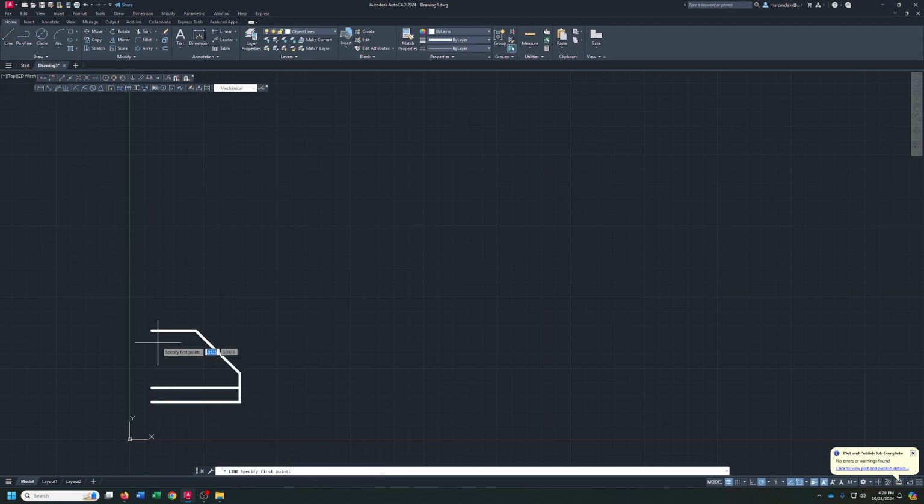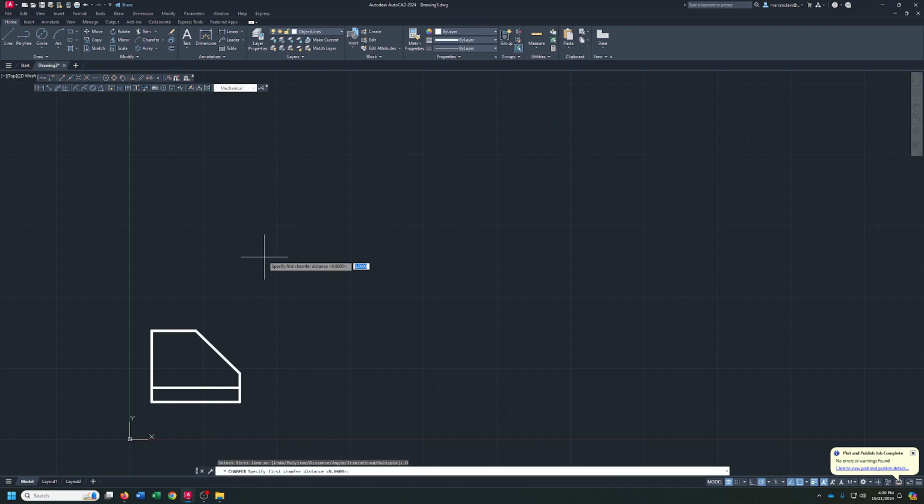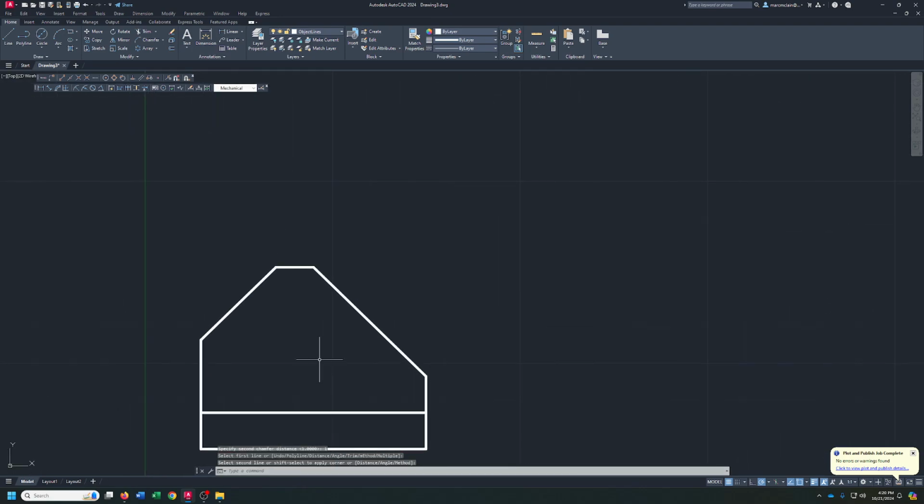Okay, now I'm going to draw a line straight up. All right, remember the chamfer command? We're going to use that again. Chamfer. And then we're going to go distance, and we're going to say 1 and 1. All right, so there's our first view.